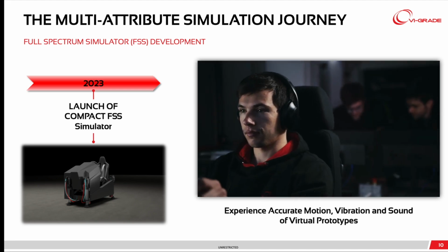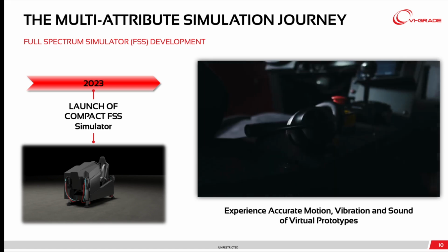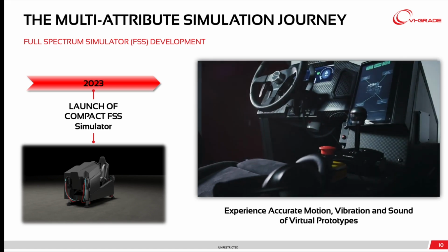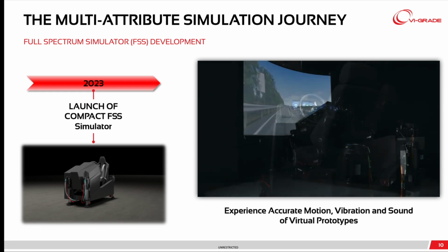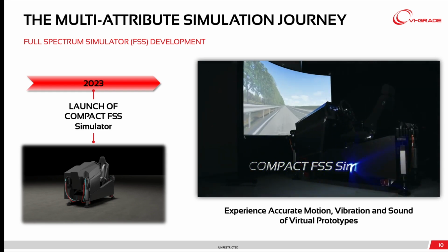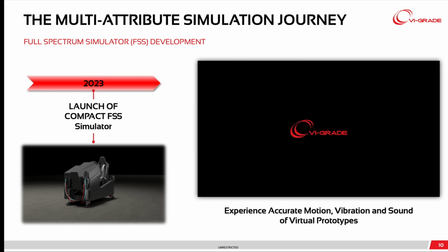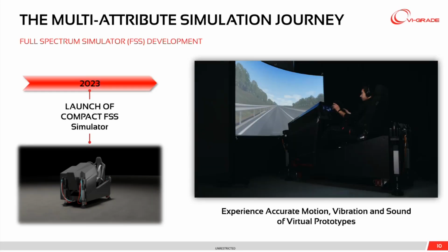And then on top of that, we equipped the touch points of the driver with shakers. We added shakers beneath the seat, on the steering wheel, and under the heel plate. So the main touch points of the driver could also replicate the vibration.